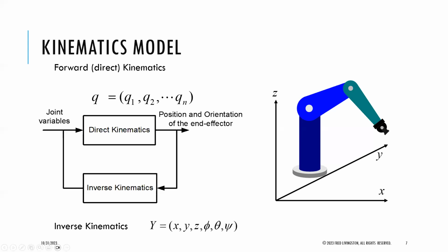And so we do some more obstacle avoidance, and that's built into most common libraries now. We'll be able to look at the entire workspace and do collision avoidance. That's another advantage of using this URDF. It has a collision matrix as well. You could describe everything with boxes, and then it's going to check for collisions before you do that movement. And because you have multiple solutions to an object, you could find a solution that doesn't involve any collision.